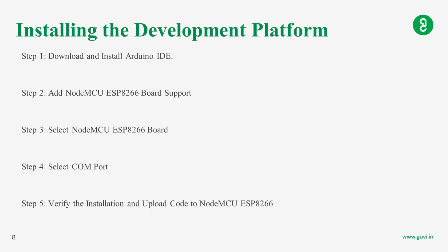Installing the drivers: run the driver installer you downloaded in the previous step. Verify the installation, whether it is complete or not. Check the device manager or system information again. Your NodeMCU ESP8266 should now appear without errors, usually under the ports (COM). Select the COM port or serial port in your IDE when you are programming your NodeMCU. Use an integrated development environment like the Arduino IDE and select the appropriate COM port or serial port that corresponds to your NodeMCU board.